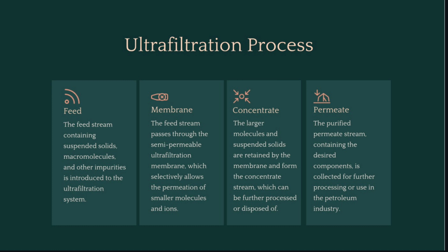Moreover, ultrafiltration uses hydrostatic pressure to force water through a semi-permeable membrane. The type of membranes that make up the ultrafiltration can be spiral wound, using cross-flow separation, hollow fiber, and tubular membranes. The ultrafiltration system works to remove contaminants with molecular weights from 300 to 500,000 Dalton. The membranes remove very small particles such as chlorine-resistant organisms, bacteria, organics, sediments, high molecular weight solutes, and other suspended solids.